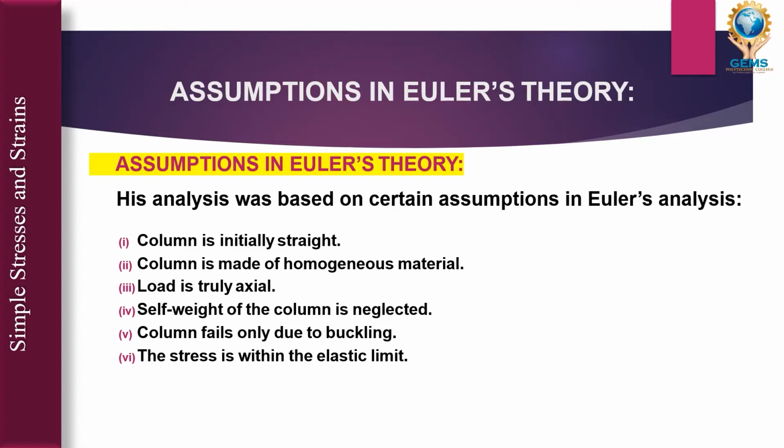Second, the column is made of homogeneous material. Third, the load is truly axial. Fourth, the self weight of the column is neglected. The fifth one is that the column fails only due to buckling. And the final thing he says is that the stress is within the elastic limit.